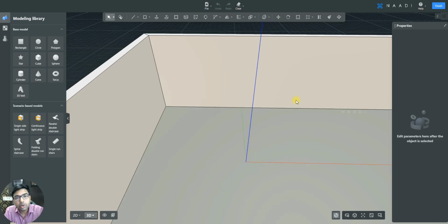So now let's look into how you can create models within your custom modeling window. For that, you first need to understand the 4 categories of modeling tools which are available in your custom model. In that, the first category of tool is your 2D geometry creation tools. In your top horizontal toolbar here, can you see this option? This is your line tool. If you place your cursor, it will open up a drop down which will have different natures of line. So your typical straight line tool, or if you're looking for an arc tool and a tool to create a Bezier curve. In that, first let's look into your line tool.